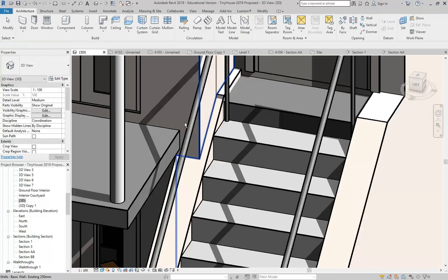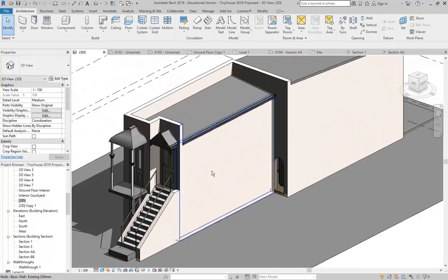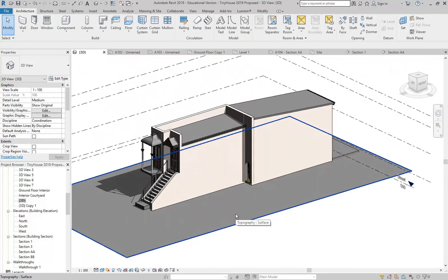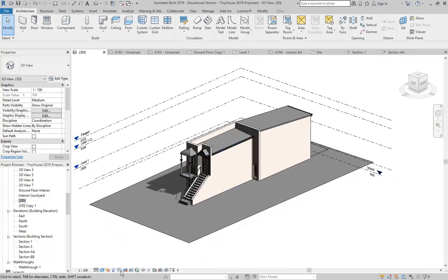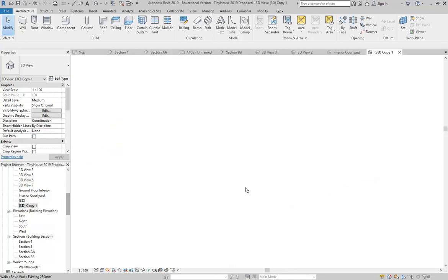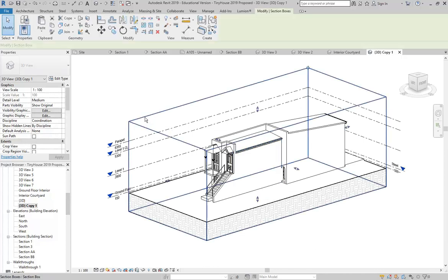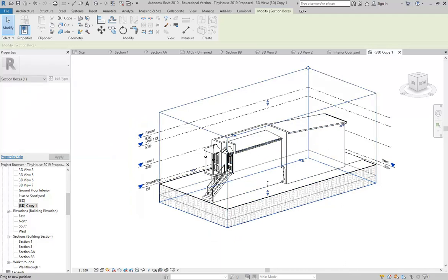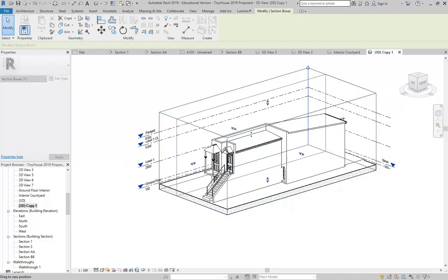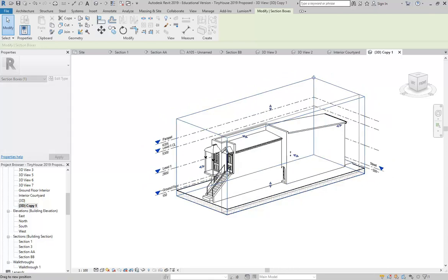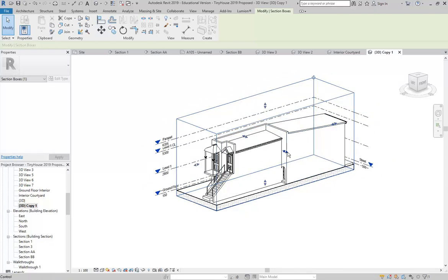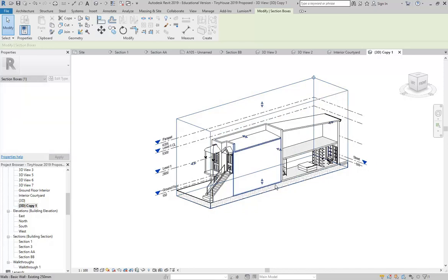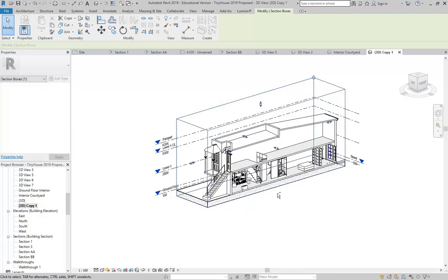And you can also do non-perspective views. So if you want a view like this, the ones you've been working in, they can go on a page. That's sometimes good. And you can crop those. So I think I've shown you section boxes. I won't go through that now, but if you've got a view with a section box, they make it a much easier thing to crop in 3D. And you can crop back into the building, start to see the interior.